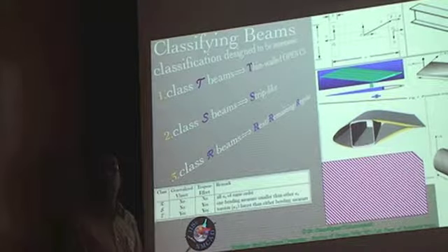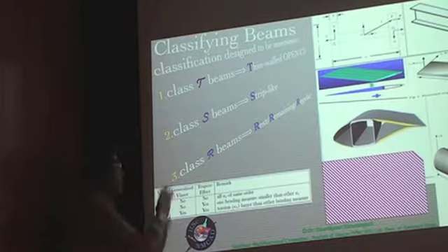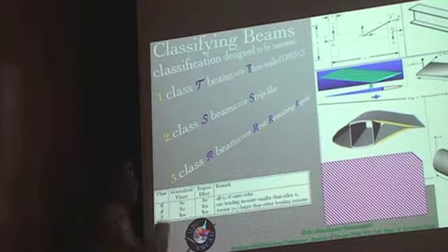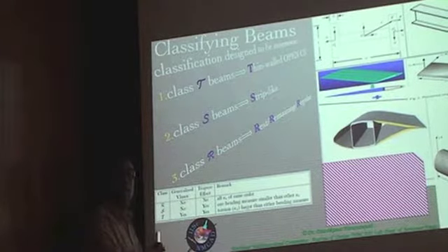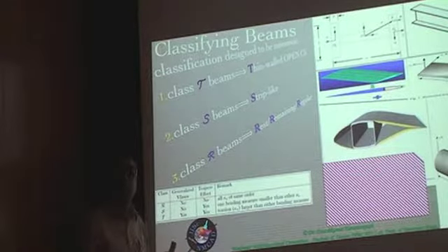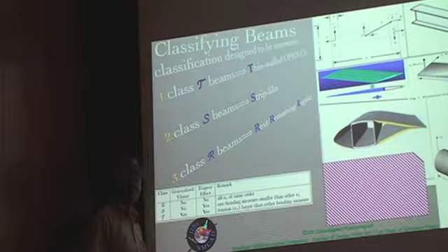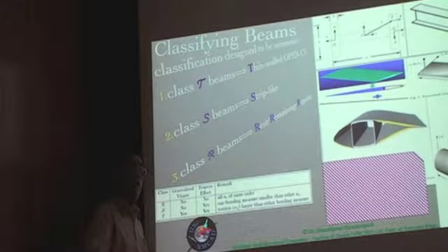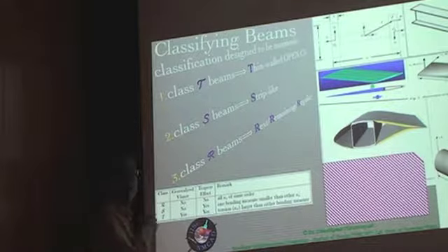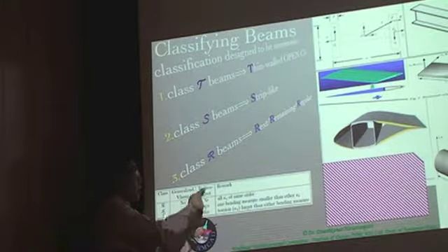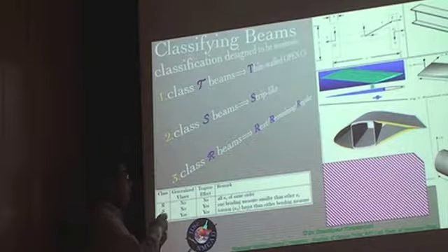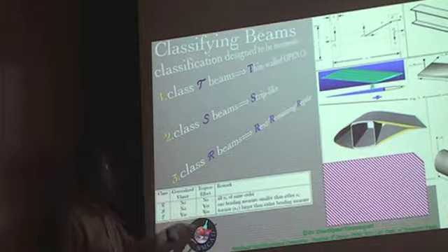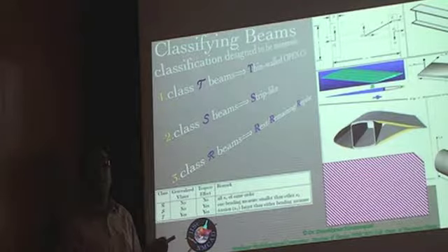Next, coming to nonlinear effects, of which the trapeze effect is an example. So trapeze-like effects, if we talk about, again for R class beams, which are solid and thick-walled closed cross sections, you will not have nonlinear effects. Or in other words, nonlinear effects, if they are there, will be absolutely negligible, in the sense that they will hardly contribute 0.1% or lesser to the energy, and therefore to the other quantities that you might be interested in, including stresses, failure, etc. All of those will be hardly affected in those cases. Whereas the nonlinear terms are extremely important in both S class and T class. And the source of these is basically, in all the cases, the nonlinear effect is purely warping.